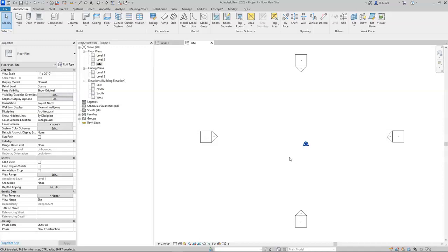The first part we're going to be talking about creating a new topo object, and then to do that we're actually going to bring in a CAD file. So this sort of circles back around to some discussions that we had when we were doing our surveying work. You can create a topography out of the survey work that we do by collecting points through any number of different methods, pulling those points into either AutoCAD or Civil 3D, which is essentially the same thing, and then taking that 3D topo that it generates and linking that or inserting it or importing it into a Revit project.